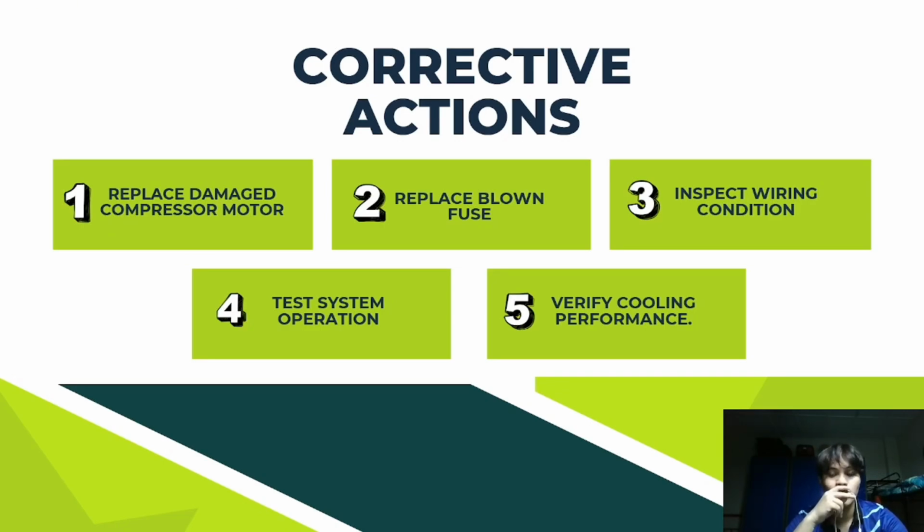And finally, verify the cooling performance by measuring the room temperature and ensuring that the system can produce cold air normally. So these corrective actions eliminate the existing faults and restore the air conditioning system to normal operation.